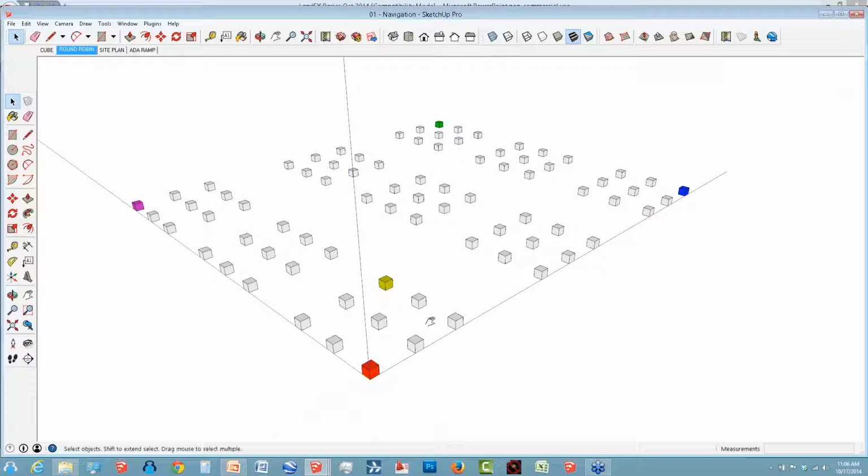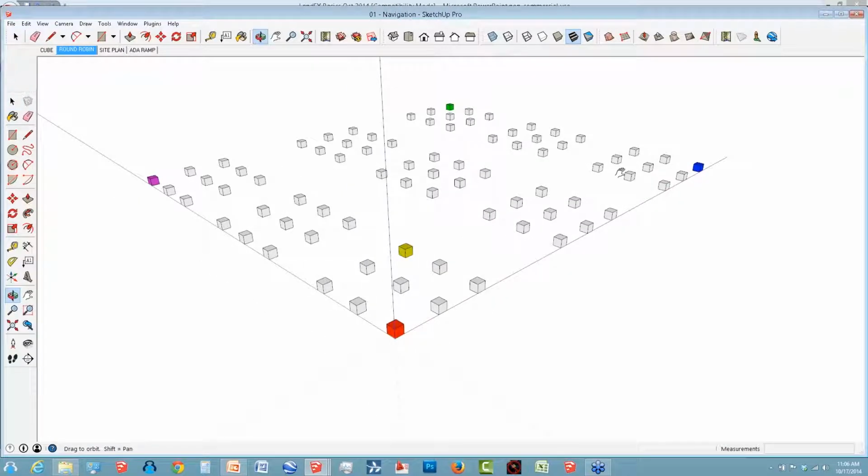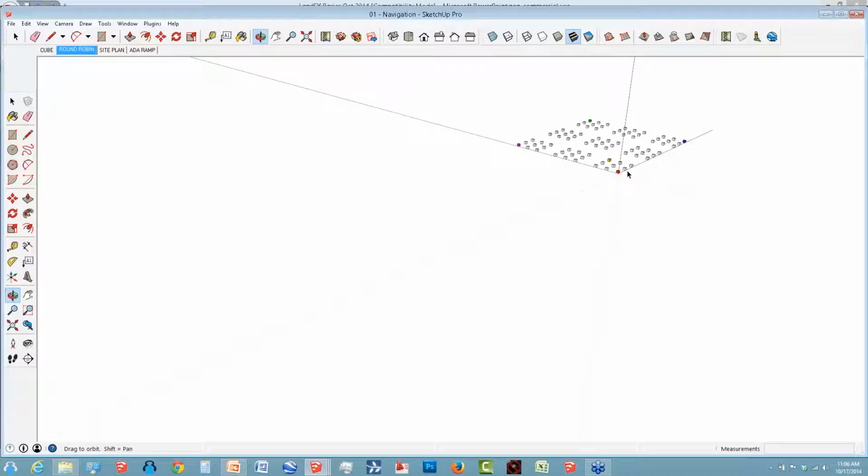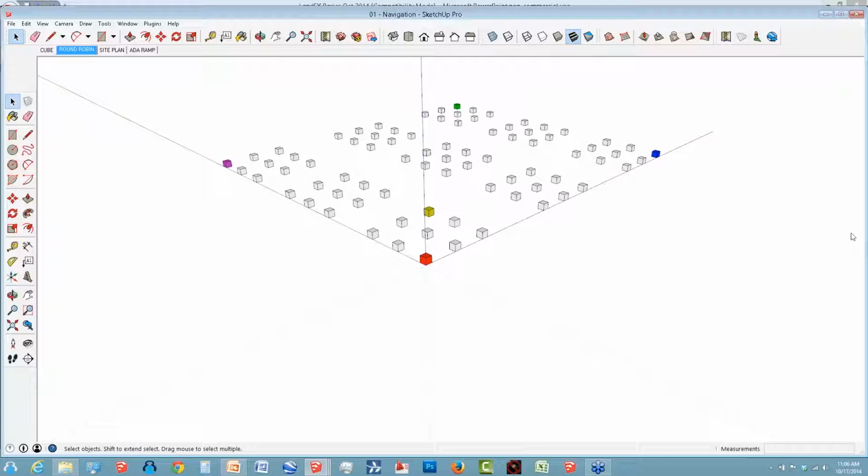And that means when you're modeling in SketchUp, the one thing I see people do quite often, and we're going to let my screen catch up here, is they put their models off to the side, it's at 10,000 feet, and then they're trying to model. Very difficult way to work in SketchUp. What you need to do when you're working in SketchUp is keep everything that you're working on centered on your screen. Basic principle. Centered on your screen and zoomed in.